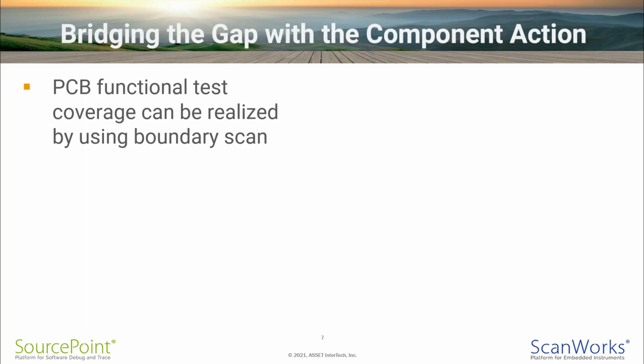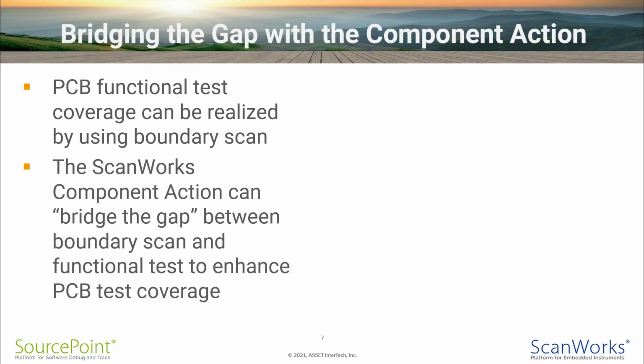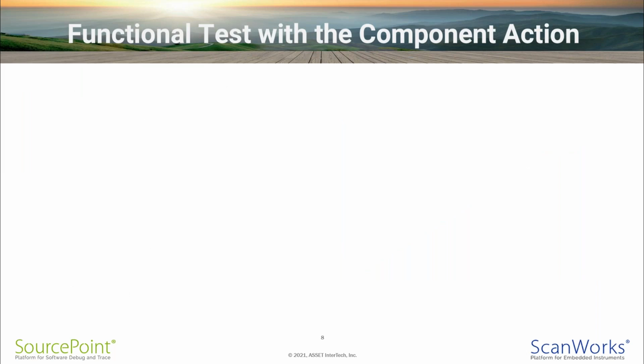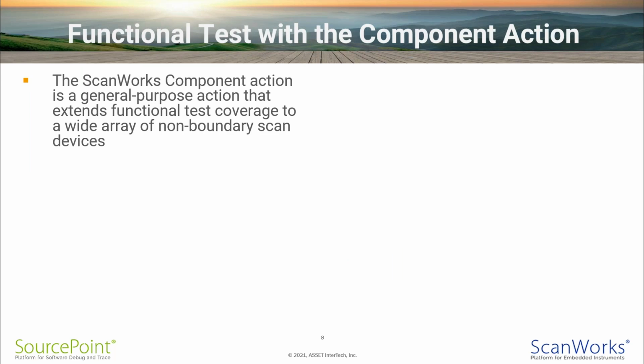PCB functional test coverage can be realized by using boundary scan, but how? The ScanWorks component action can bridge the gap between boundary scan and functional test to enhance our PCB coverage, and again, to drive our test coverage higher toward that 100% goal. What is the ScanWorks component action? The ScanWorks component action is a general purpose action that extends functional test coverage to a wide array of non-boundary